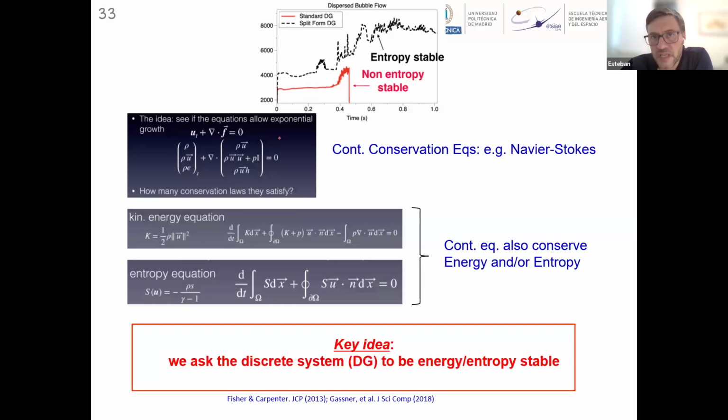That means that if you were to run these cases with a normal formulation of incompressible Navier-Stokes plus Cahn-Hilliard, eventually your solver might blow up. It might run for a while, but then if the interface starts showing some oscillations or some high frequency features, the solver might blow up and you end up without any result.